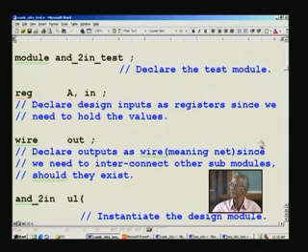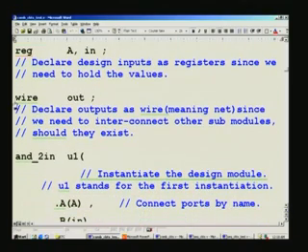I will come back to this once again, because unless I explain this, I can't explain that. Right now, you have to call the design module as such. That is called instantiation in Verilog coding. This is the design module we started with the .v extension, but inside we had declared the module name as this alone. So, when you call any of these design modules, you call only by the module name, not with the file extension.